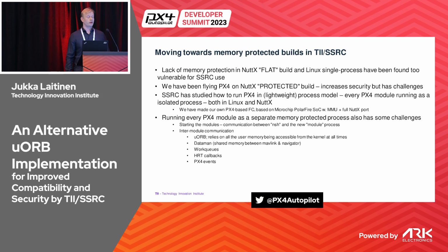But running PX4 in this process model has some challenges, of course, because probably nobody has tried that before, and that kind of model in the embedded world is not so common. I have listed some of the issues here, but one of the big things is the uORB. Even though I promised that I won't talk about what it is, it's the common publish-subscribe interface, which is used by basically every module and driver to pass data to each other.